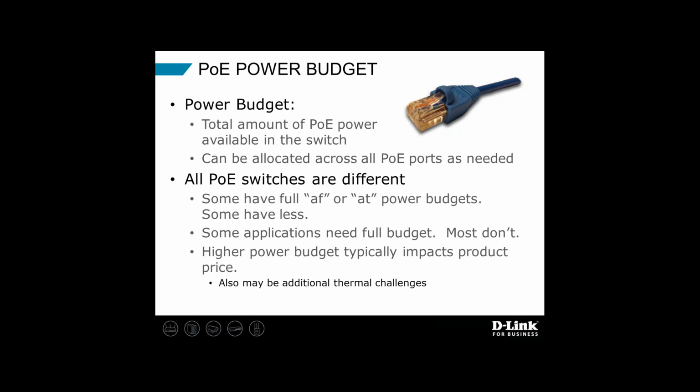Most IP cameras, for example, I'm running an 8-port switch at home, and I have 8 IP cameras, and each camera is drawing between 2 to 6 watts. So I don't really need a lot of PoE budget in my switch.